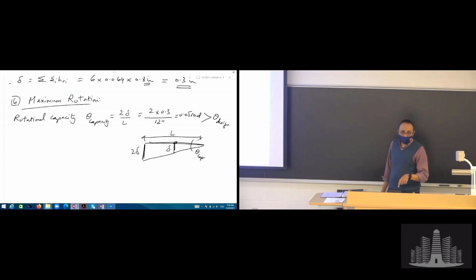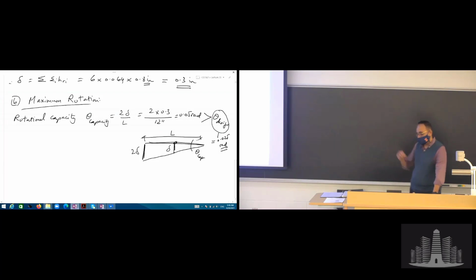Now, everything we're doing here, the analysis of the compression, everything, we did not look at what system. Is it a beam deck system? Is it a box girder system? Is it steel? Is it concrete? We don't know. We're just looking at the bearing. But your theta design is something that comes from your analysis of the system. And that showed, in this case, this to be equal to 0.25. That was given to you earlier in the notes, in the statement of the problem. So obviously, our capacity is greater than what the analysis shows, so we are okay. That is a good result there.